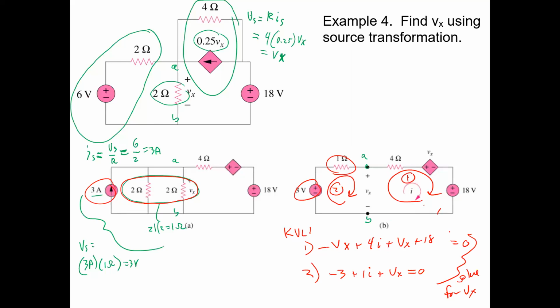I advise you not to. Just be aware of that, because look at how we had to be careful about that. My naive approach would have been to say, well, if Vx is the voltage across that 2 ohm resistor, and we transform that into a 1 ohm resistor, don't we have to put Vx over here? Doesn't that kind of make sense? Wouldn't you think that the Vx should follow the resistor? But it doesn't. It actually adheres to those 2 nodes, right? If you're aware of that, it's just a little more complicated to keep track of, and it'll actually work out okay.